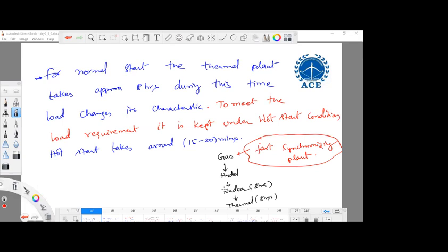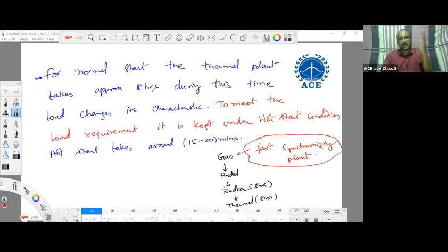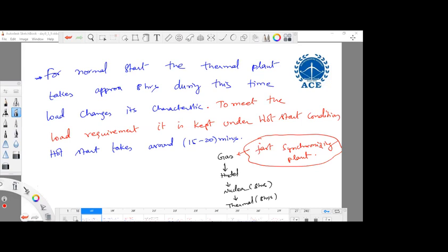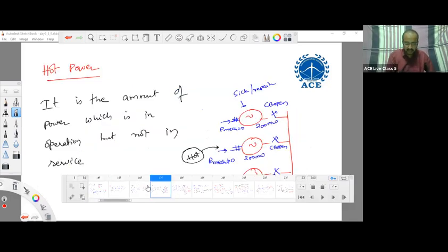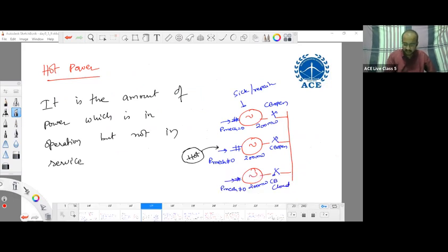Another doubt, sir. In any example of spinning power, spinning power means the power available at that bus bar and delivered to load. Suppose this mechanical power of 200 megawatt is generating and it is delivering to load. This becomes the spinning power here.